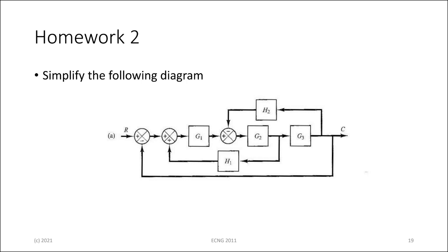Try this one. I have the solutions for it. Remember, you want to get the feedback block, a positive feedback or a negative feedback block. You want to be able to manipulate everybody to get it into that, one little unit at a time. So for this one, for instance, if you just move this out of the way, then you have G1, G2, G3, and H here that you could play around with.